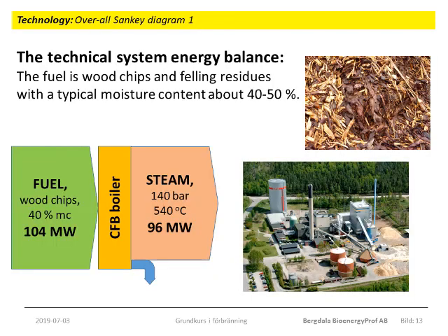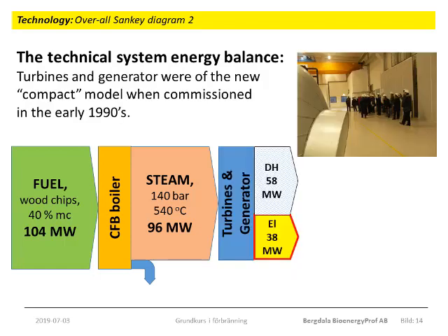And the case is a 104 megawatt thermal circulating fluidized bed unit, Sandvik 2, at Växjö Energy in Sweden. The boiler house and the flue gas losses amount to approximately 8 megawatt, so the maximum steam production is about 96 megawatt.